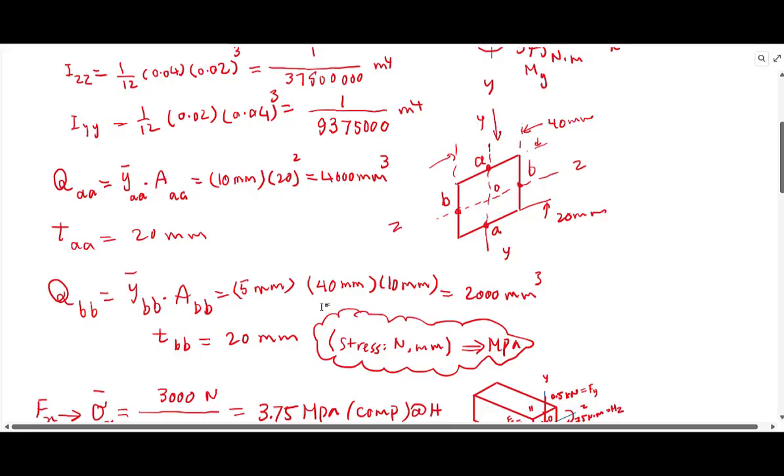And like I said, we keep all the dimensions in millimeter, all forces in newton, such that the calculated stress becomes megapascal. All right, next we just calculate stresses.